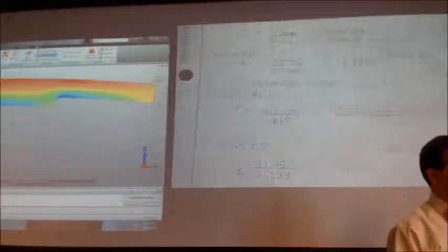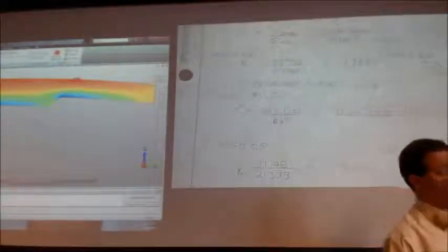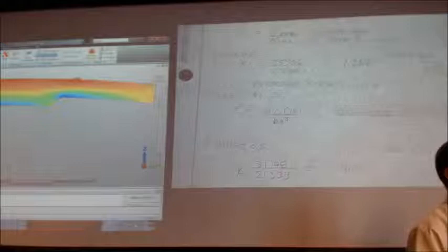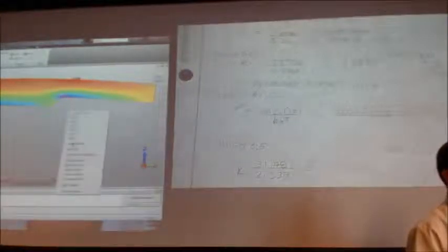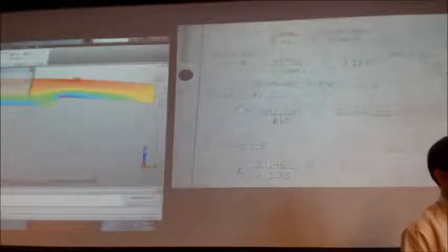And the way that you find what my stress is there is you're just going to pick max. Well, so the max isn't in the right place. So the way that you pick the max then is, let's see, I'm on nodes, okay? So you're just going to come in here and pick a group of nodes. And then you're going to say inquiry. Oh, I should switch over to the other side. Hang on.